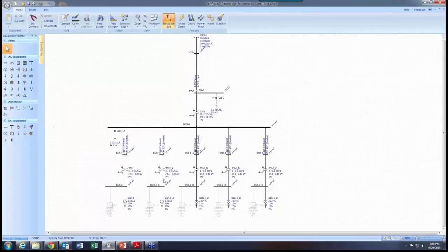It's not really a large file. Usually, as discussed before, you would be considering either FERC 661 rules or IEEE 1547 rules. Regardless, you would come up with some power factor requirements, voltage requirements, and frequency requirements, and let's say you cover all of them in your power flow